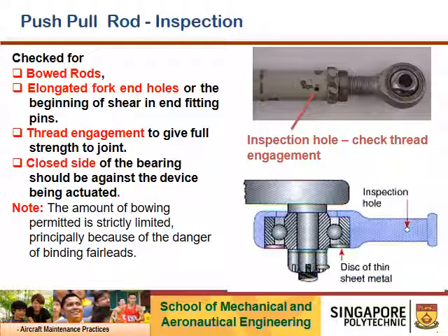All right, push-pull rod inspection. Make sure that you check the rod is not bowed. What do you mean by bowed? Normally a rod itself should be straight. If due to prolonged compressive load it takes a bow shape, then you have to change the push-pull rod.